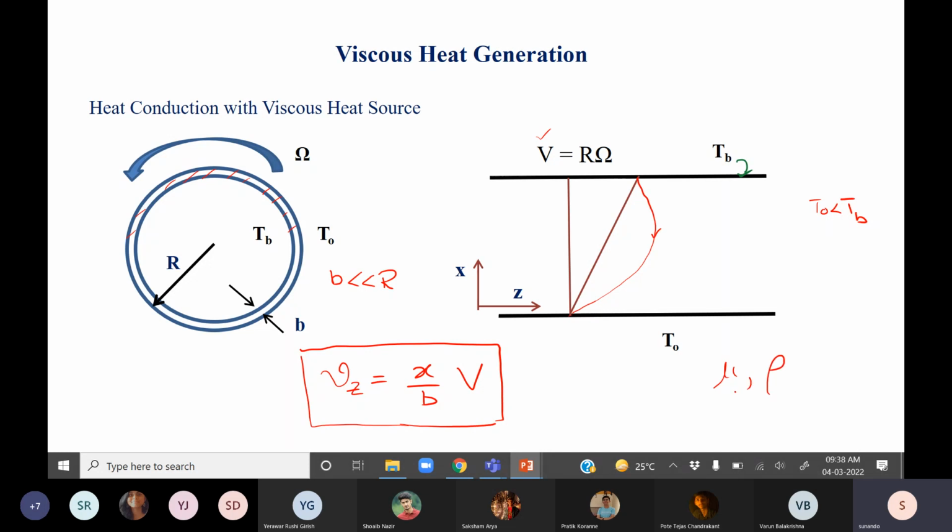More importantly, it's this mu which you would like to see how it behaves with temperature, because viscous breakdown of a lubricant is when suddenly the viscosity drops to a value where it will flow easily and thereby not impart any lubrication for flow in between the two. So, is there any question on the development of this problem?